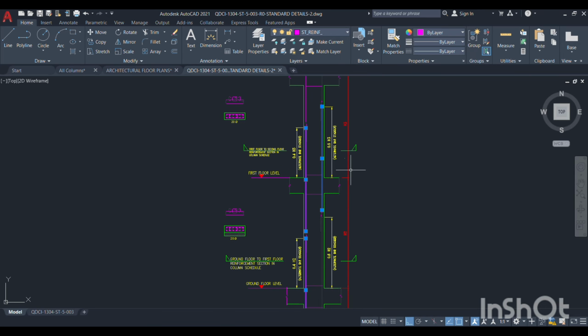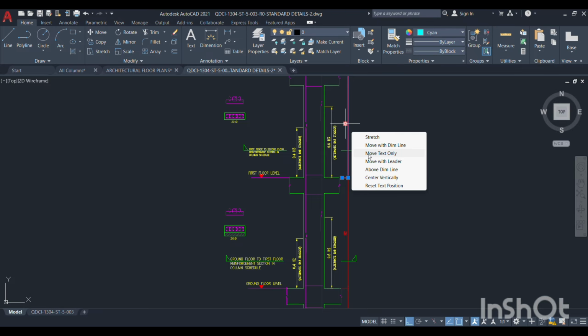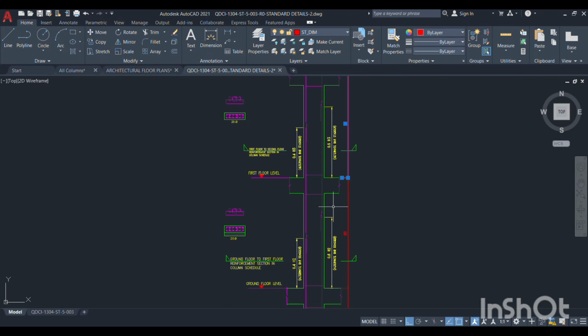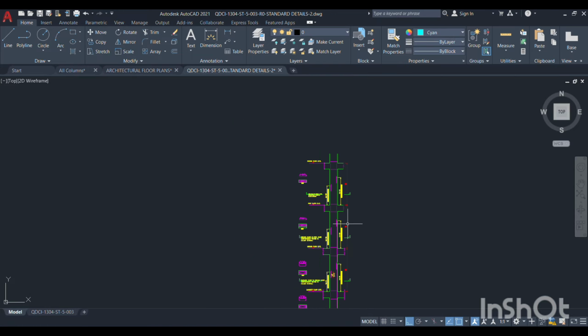For this, whatever the longer rod we have placed, for that we have taken 0.6. Now here we will take 0.4, and whatever 0.4 you have taken in the previous, for that 0.6 will be taken from the rods of the first floor below. And similarly for the first floor above, again it is 0.4 times of this first floor height, and 0.6 times of this first floor height. So this is the concept of taking column main rods.